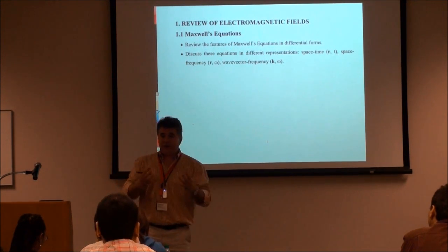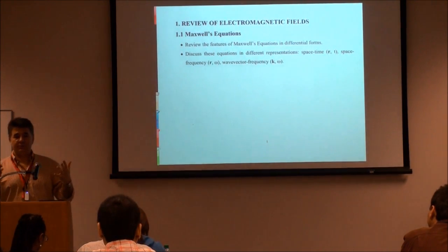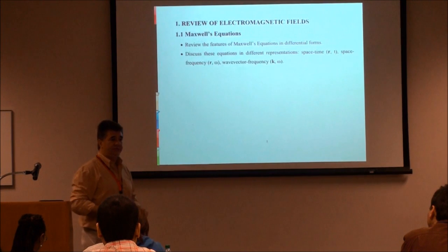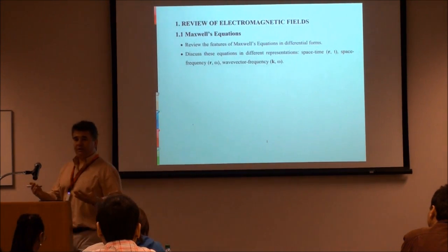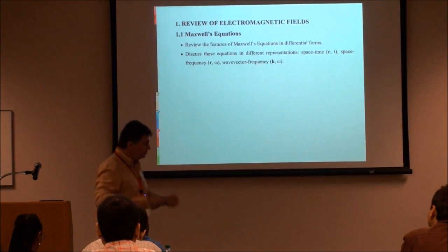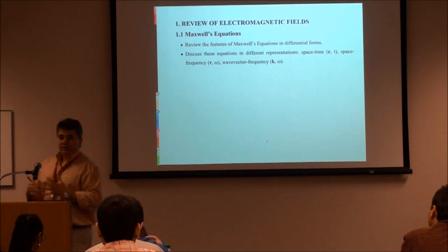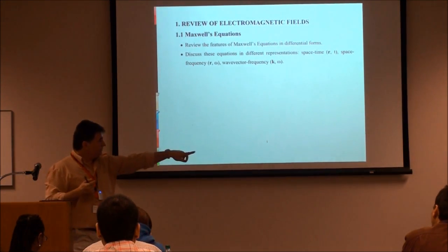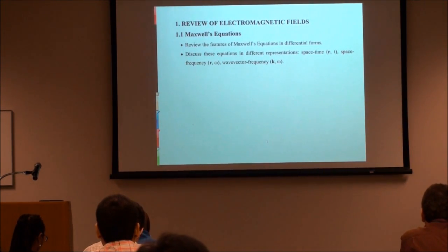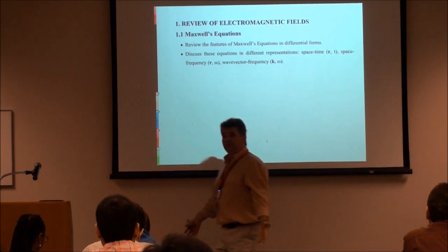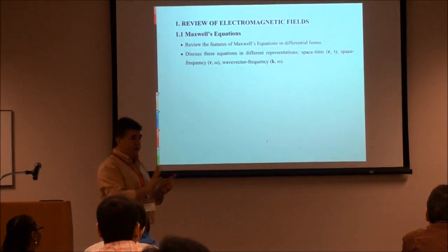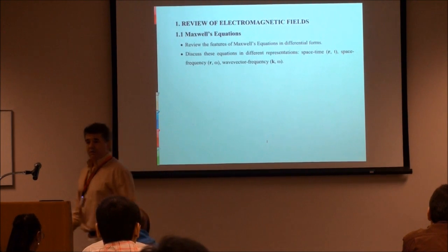The Fourier transform means that I can take a signal and decompose it into a summation of cosines and sines with varying frequencies, amplitudes, and phases, which means that I can take the problem, solve it for each frequency, and add up the results. Again, the superposition principle due to the linearity of the problem. Now we brought the two together. The Green's method and the Fourier transform allow us to express this convolution in terms of a product, which is much easier to do. The system basically acts as a filter in the frequency domain. That H tilde is the transfer function that somehow is modifying the frequency content of your input.